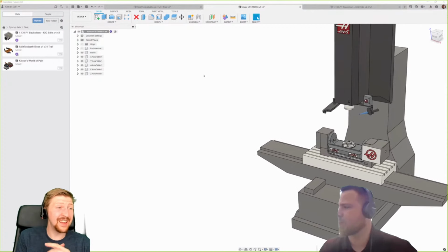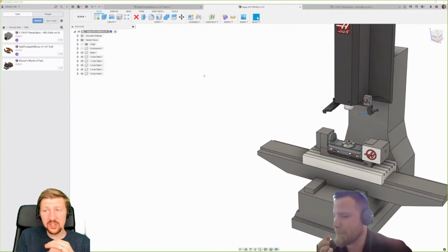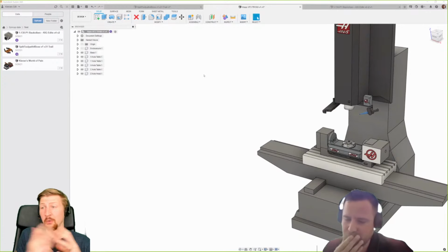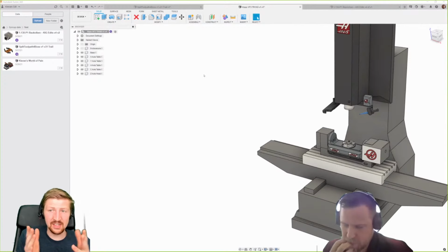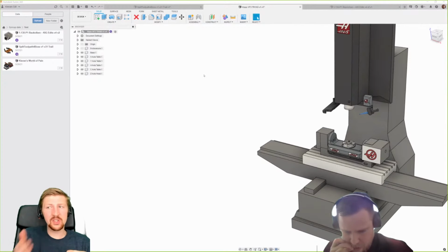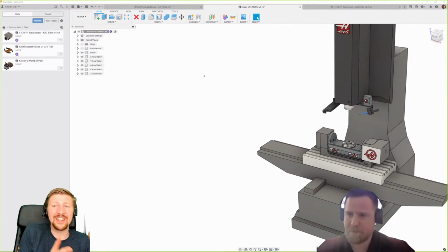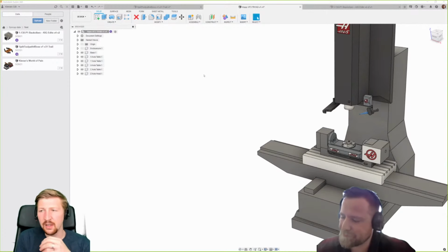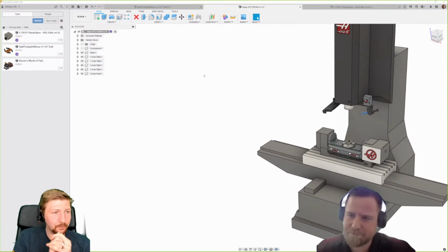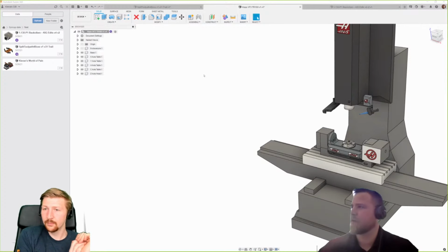One question that's come in: is this available with mill turn? Well, if it is a standard mill turn, then it's more a milling machine than a turn, so we can simulate the milling portion of that. If it's a turn mill, it's probably not going to be able to be defined correctly, because that will naturally be a lathe configuration with a spindle. Correct, 100%. Richard nailed it there. I don't need to add any more to that.